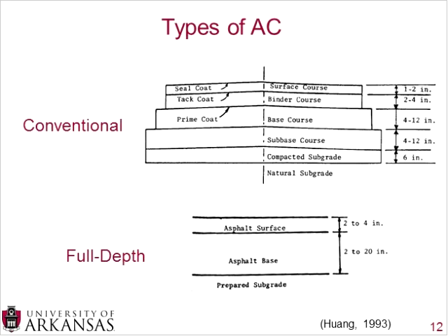Unless you construct one very, very quickly after another, you may have delamination where the surface course can literally lift off of the binder course if you're not careful and if you don't have that seal or tack coat.